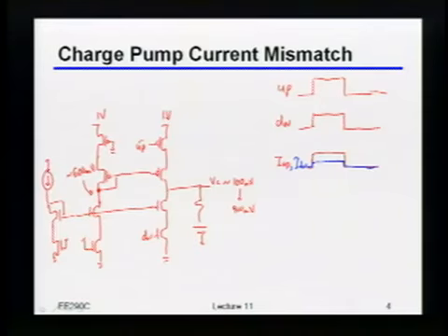When I up equals I down, right? Okay, so is it I up equals I down, or what is the loop actually enforcing? The charge is this. There we go. The loop's enforcing that the charges are equal, right? So how do I make the charge equal if the up current is larger than the down current? What do I have to change? The pulse width has to change. Which one has to get wider? Yeah, that's right. I down has to get wider, because since it has less current, you have to integrate it for a longer period of time to actually get the output to be correct.